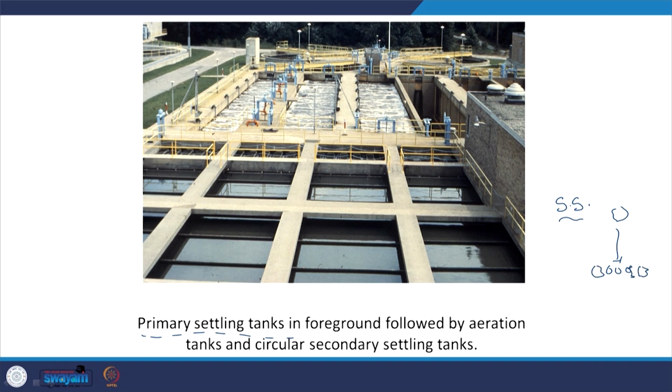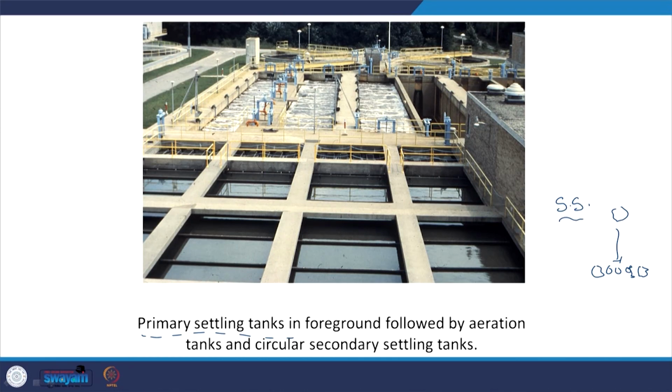And then there are organic compounds which I will try to remove using the microbes, right. Microbes, though similar to us, they need oxygen, which is an electron acceptor, to be able to let the redox process go through. So, that is why I am going to pump in air, that is why you see this particular turbulence.